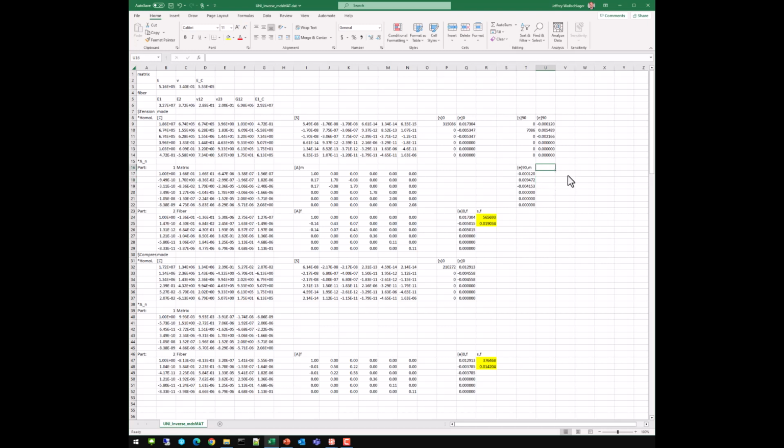Okay, but I need to calculate my volumetric strain, or J1. Well, that's just equal to the sum of the normal strains. So I have in the matrix phase about 5,000 microstrain volumetric strain. And I need to calculate my mean stress. In order to get my mean stress, I need my bulk modulus, K of the matrix. So K is equal to what? E divided by 3 times (1 minus 2 times Poisson's ratio). And so that's my bulk modulus. And so my bulk modulus times my volumetric strain gives me my mean stress.